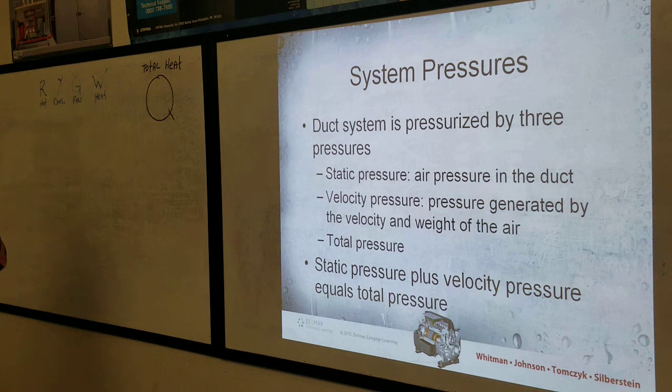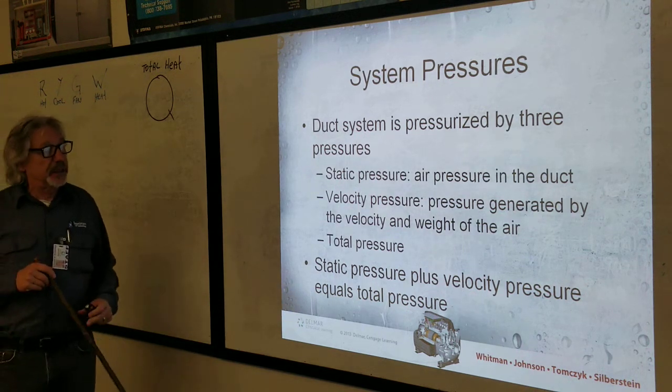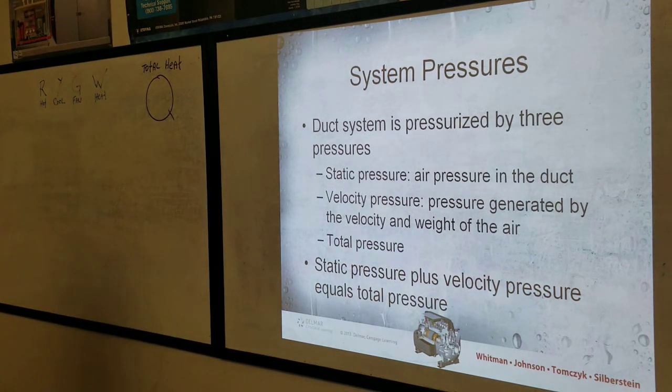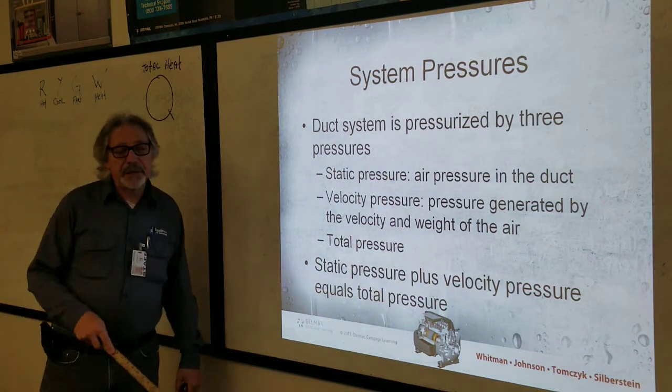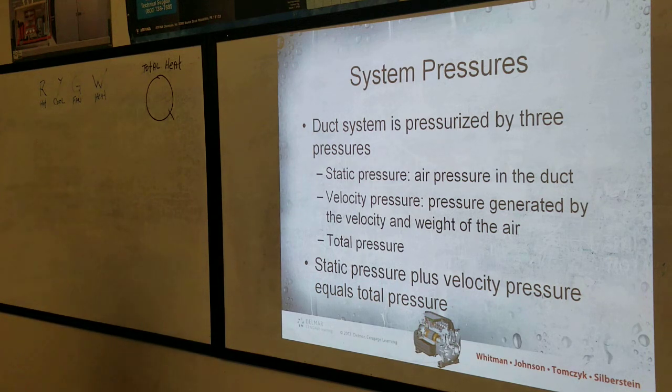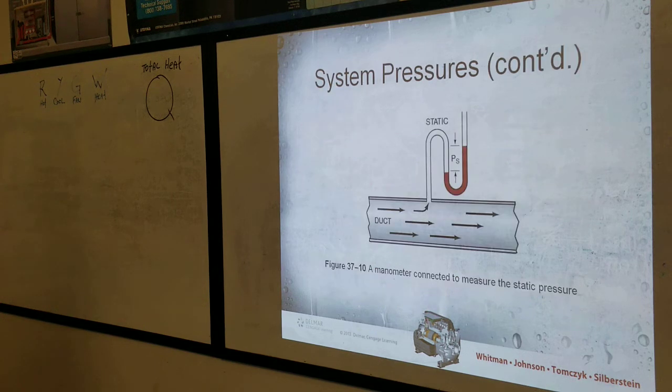Okay, we kinda went over this a little bit last week about the pressures in the ductwork, velocity and static, and total pressure. So basically, static pressure plus velocity pressure is gonna equal total pressure. So we're gonna have velocity pressure and we're gonna have static pressure.